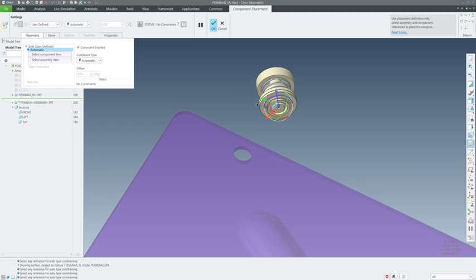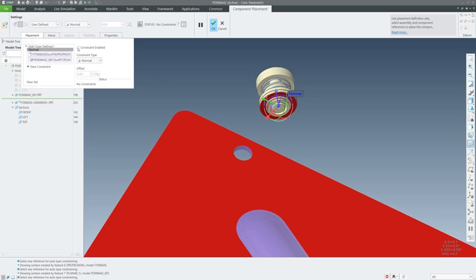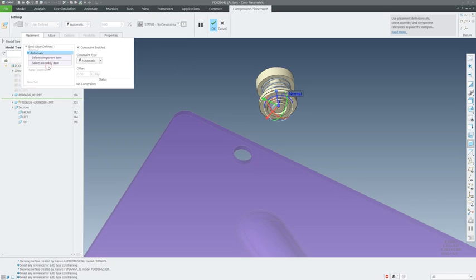So before you apply your constrained surfaces, you can disable that constraint not to be applied right away. Then you click on surfaces, but the model doesn't go away, because the constraint is not applied yet. Then your second constraint, which is going to be the cylindrical coincident. You can also disable this for a second